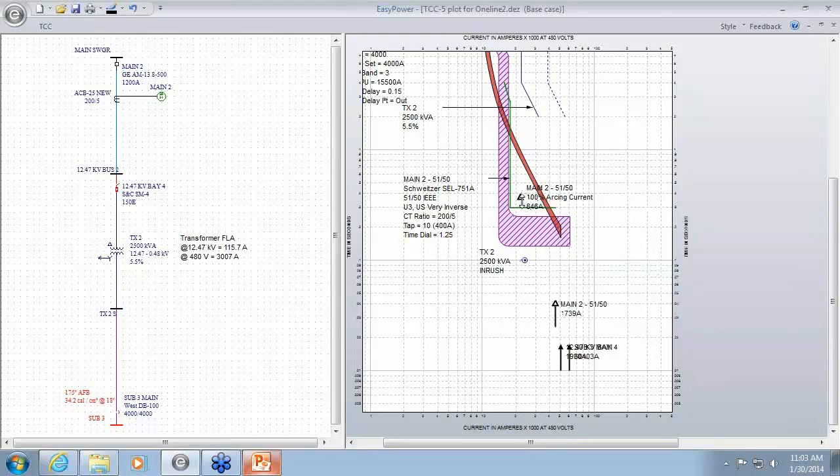So that's what's nice about the TCC. You can tell where your currents are and how you need to adjust your curves to see what the different hazards will do for you. So in this case, I've significantly reduced my incident energy with just changing the settings in the relay.